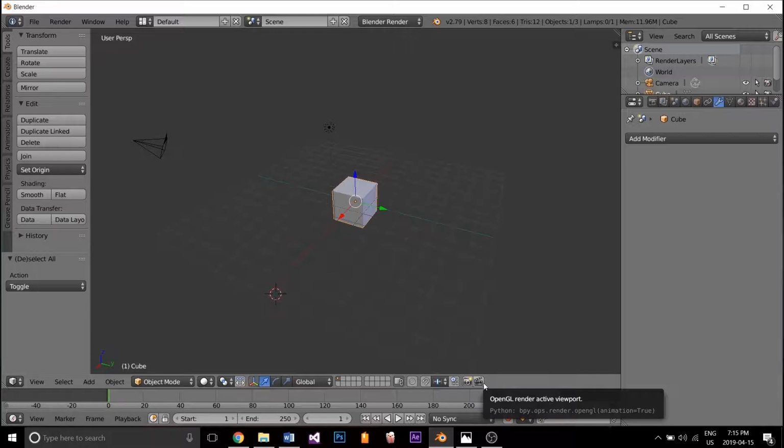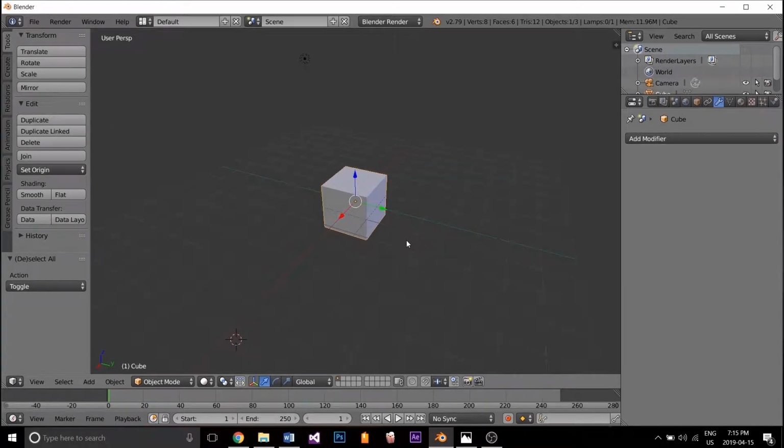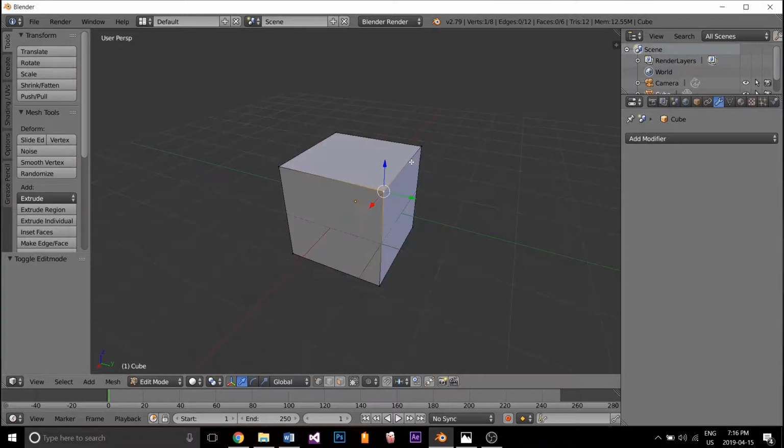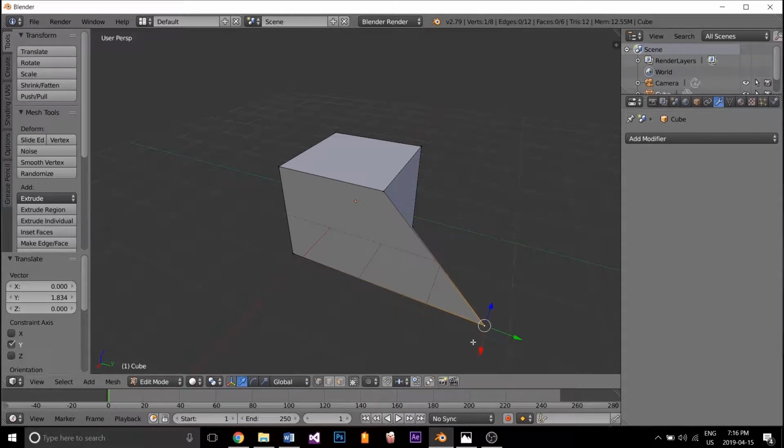do things. So in our scene, we have a box, and if we tap the key on our keyboard, tab, we can actually go into the edit mode. This is where we can begin our 3D modeling. Okay, so to go in, we now have our different vertices that we can click, and then we can achieve this by right-clicking, and we can click 1. Now we can grab on the y-axis or the x-axis, Z, so forth. If we hit Control Z, we can go back and undo our work.